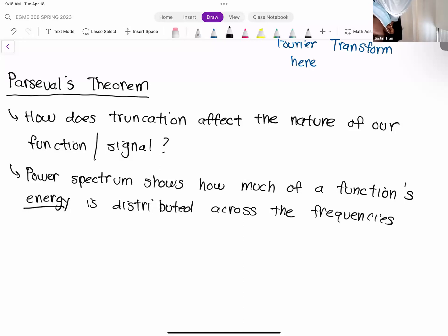Think of our frequency response test. If you take a structure and you literally kick it, you're introducing energy into that system. The kinetic energy of your foot when it strikes the structure gets transferred into that structure, and as the structure dissipates that energy, it'll vibrate. That's essentially what's happening from an energy point of view. The power spectrum tells you that if you have excess energy in your system, it tells you how that energy is distributed among the frequencies.